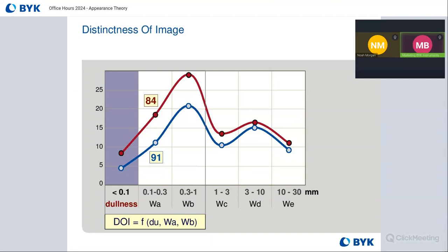So that's a good question. It depends on what you're really trying to look for. It also depends on what you're measuring. Usually if color is involved, you want a color measurement device, or if it's an effect pigment that you're using, you want a multi-angle color measurement device.